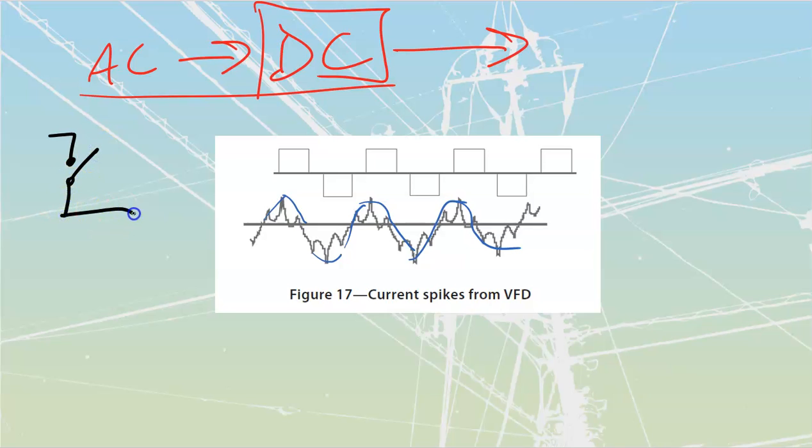And then from there, you're going to take it down. You're going to do all of your sub-distributions, and then from your sub-distributions, you're going to go into your distributions outside of that into panels, etc. And usually you can start to, after a while, clump where you're getting the most disturbance, less disturbance, and even the least disturbance across there. And then you can just work your way backwards to try and find what it is. And then look at the types of machines that they have and if they're tied to time.